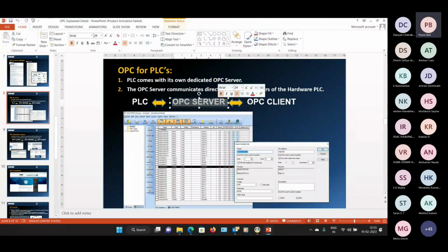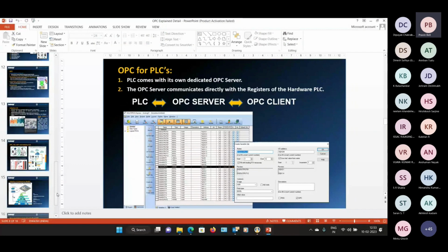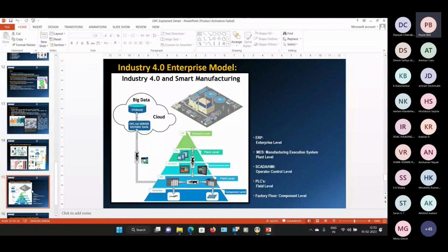If you see Simulink, most of you must be using Simulink. Simulink has an OPC toolbox. Most of you may not be aware, but go to Simulink. Simulink, I think in Simscape. No, not in Simscape. In the basic Simulink list of modules, you'll see OPC toolbox. And it's a very simple procedure of communicating data between Simulink and Automation Studio by using that OPC connectivity.